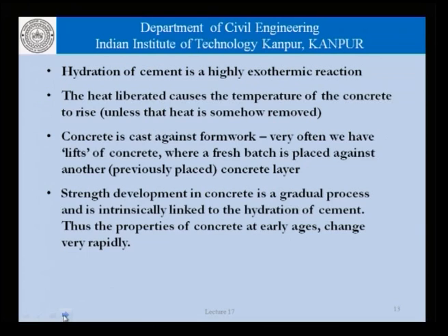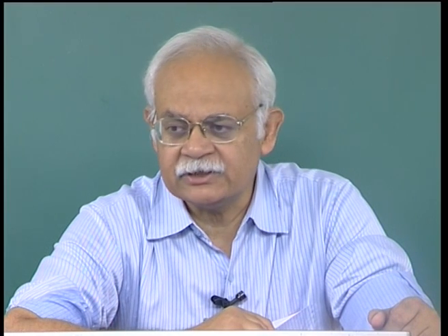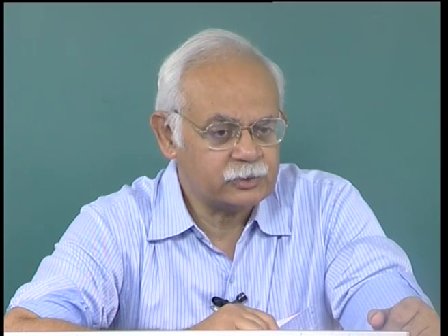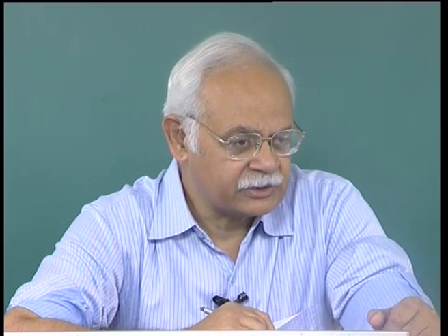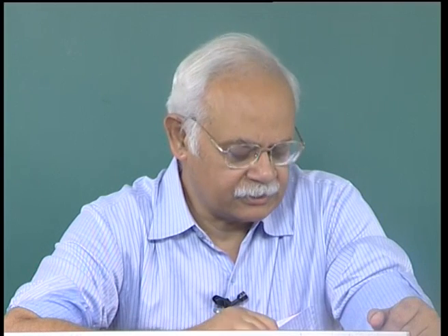Strength development in concrete is a gradual process and is intrinsically linked to the hydration of cement, and thus the properties of concrete at early ages change rapidly. And therefore, if we are talking about considering or studying the effect of a certain property of concrete, then we should really take into account the time dependence of that property, especially in the early stages, and that is where mass concrete considerations are very important.